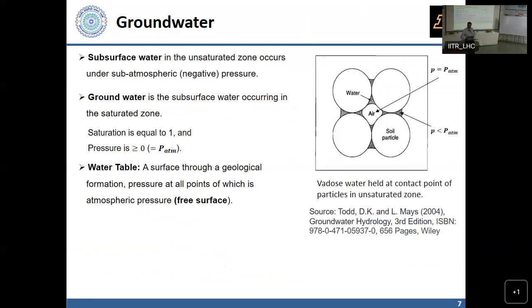And if the pore space is being shared by both air and water, even for unsaturated flows for this particular workshop, we will assume that the air phase is not going to be very important in the sense that air everywhere is able to escape to the atmosphere so that it's always atmospheric pressure. And therefore the air space doesn't get compressed and build pressures and so on.